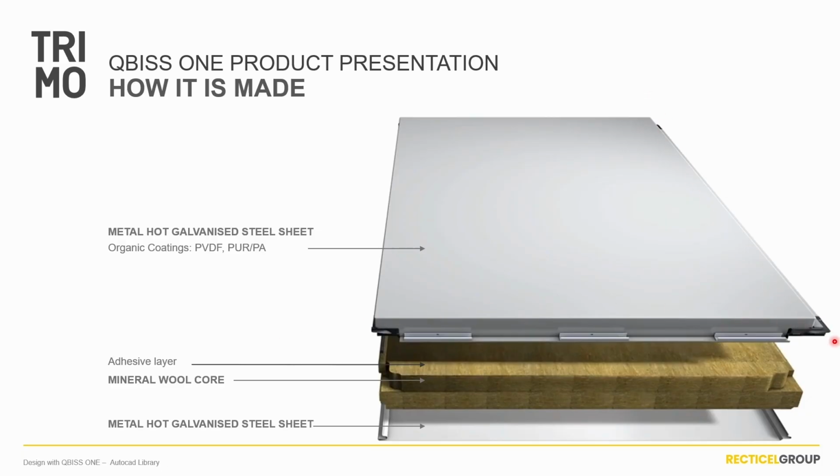When panels are assembled on-site, they form longitudinal and transversal joints that ensure structural integrity and weather tightness. For cost optimization, widths are carefully combined, especially those with differences of just 1 millimeter, allowing precise design flexibility while minimizing waste. Basically, to summarize, the fewer modules you have, the better price you have.